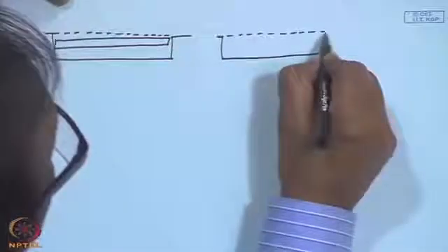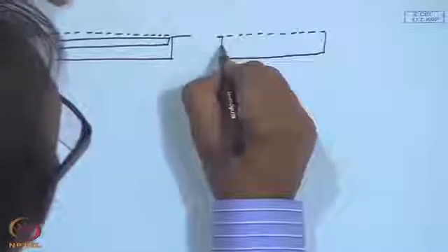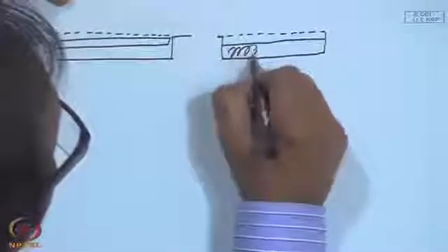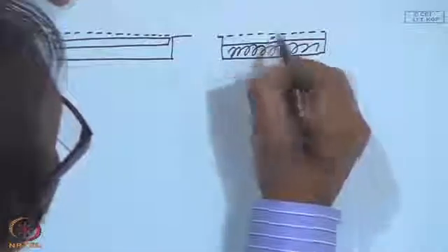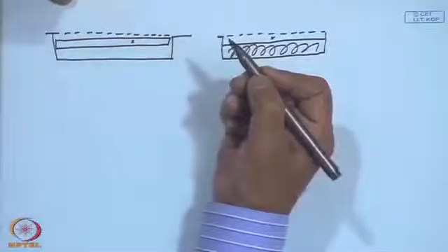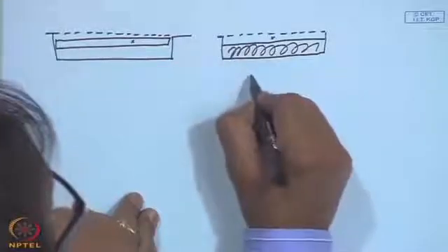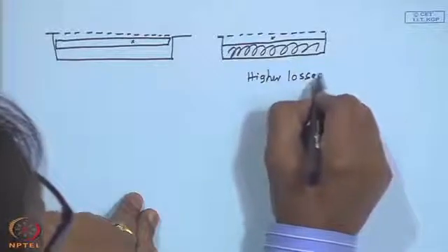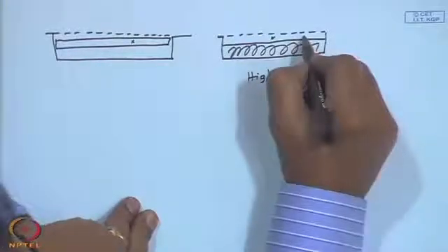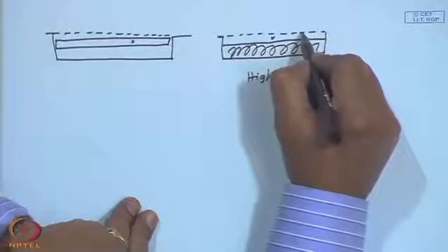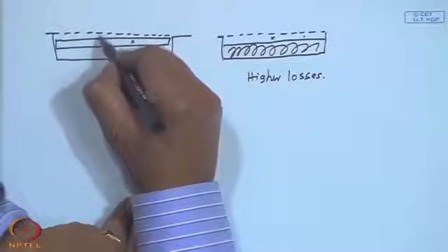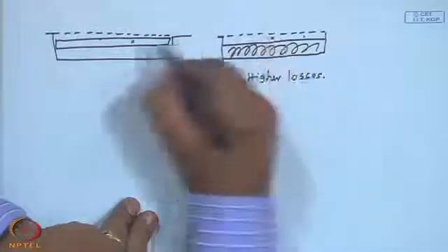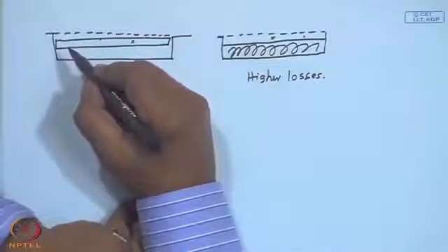With only one absorber. Flow is through this and flow is through this. Obviously, here there are higher losses. This being hot air is directly in contact with the top radiation and convection losing surface, the glass cover. Whereas, here at the absorber there is a free convective loss instead of a forced convection loss. So, this is expected to be better. So, this may become comparable to something like this.